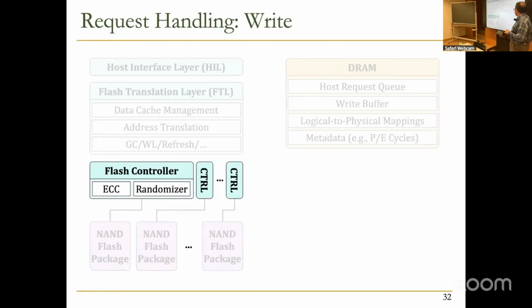At least you might be able to recover if you add some techniques, some ECC stuff, but that's not easy. Okay, so after going through FTL, then we need to go into the flash controller. Remember that we were writing the data to the flash memory. So the flash controller actually does signaling, which is a very important thing for NAND flash packages. So you need to do some signaling such that you can communicate with this NAND flash package. And with that, you need to have this kind of analog support to send some pulses, importantly, for NAND flash packages such that they can work.